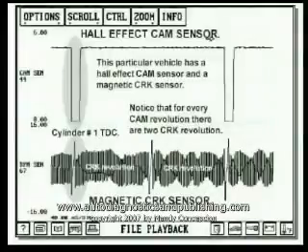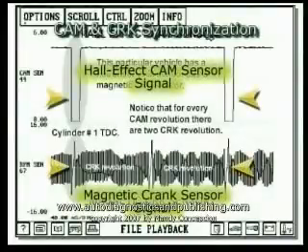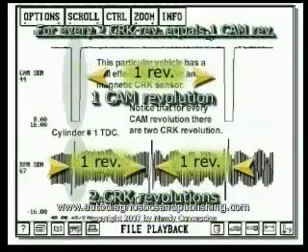Another important aspect of speed sensor signals is the relationship between the cam and the crank sensor synchronization. Remember, when ascertaining a relationship between these 2 signals, there are always 2 crankshaft revolutions for 1 single camshaft revolution. These 2 signals have to match precisely.